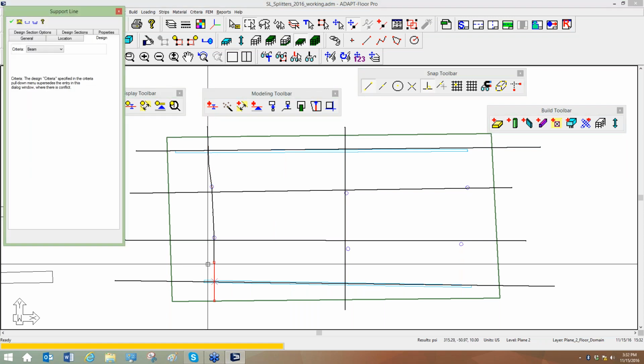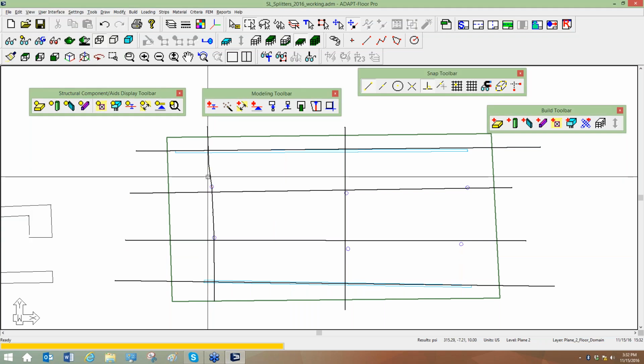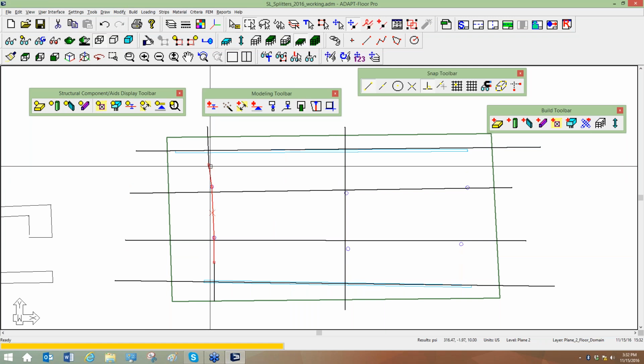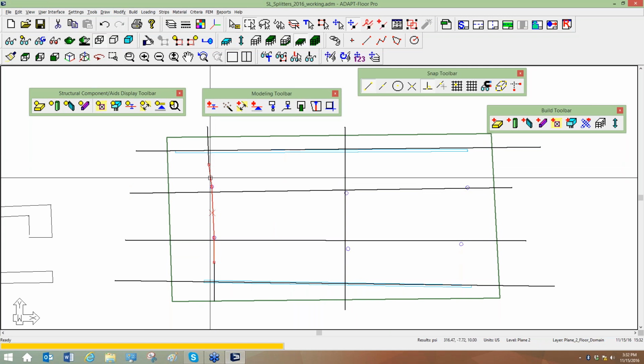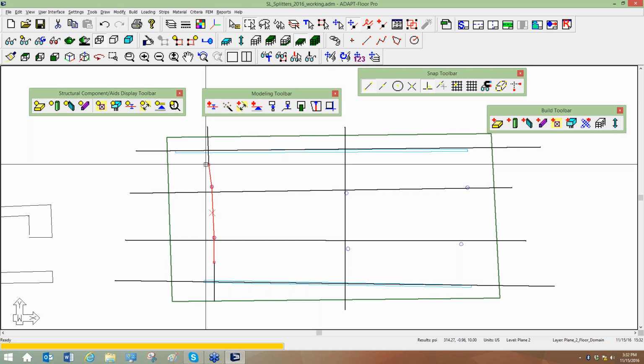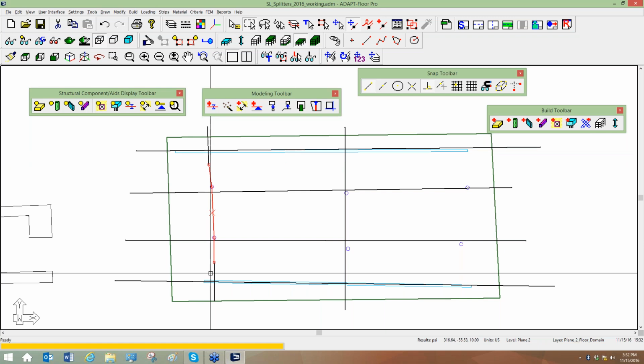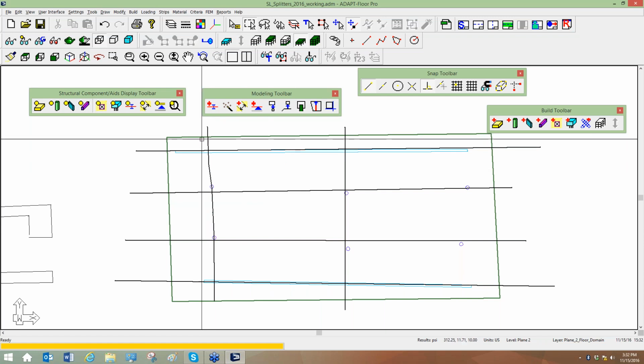and then one-way again. This would result in incorrect lengths of reinforcement over this column because the span length is defined from there to there. So that would be the negative outcome of this type of input, but you would still get the right areas of steel related to the design types for those strips.